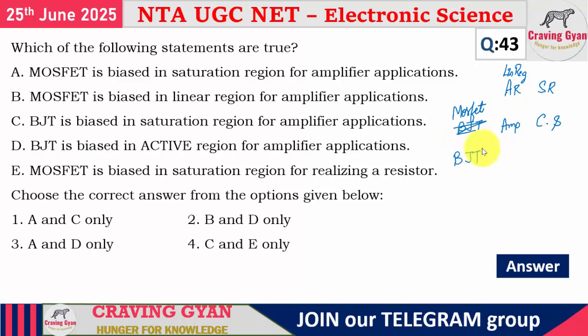In the linear region, if you are operating the BJT, it will be acting like a current source. In the saturation region, it will be acting like an amplifier. So, MOSFETs in a saturation region will be acting like a current source, right? So, "MOSFET is biased in saturation region for amplifier application" is wrong.